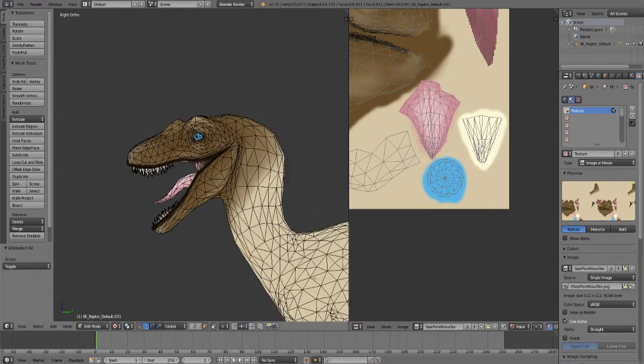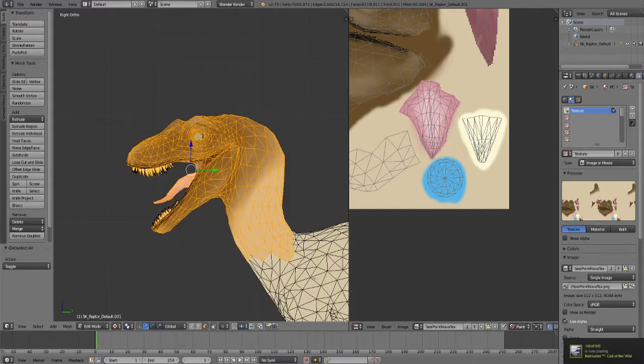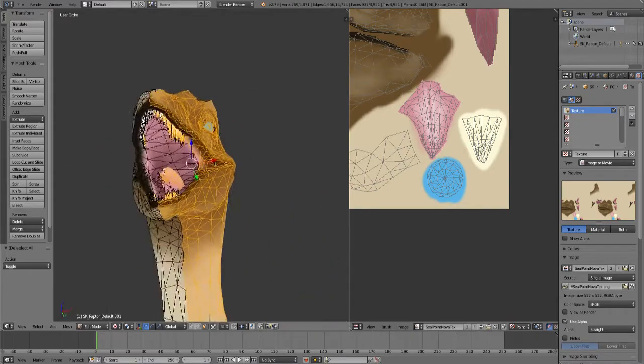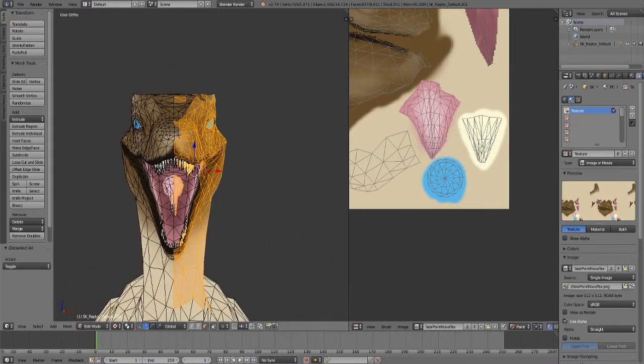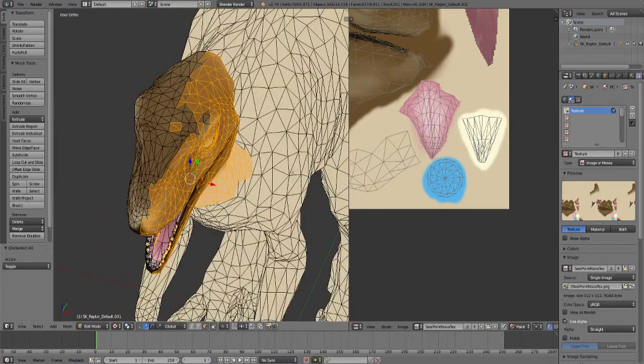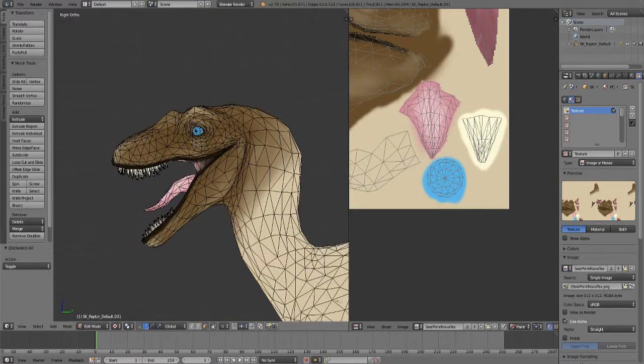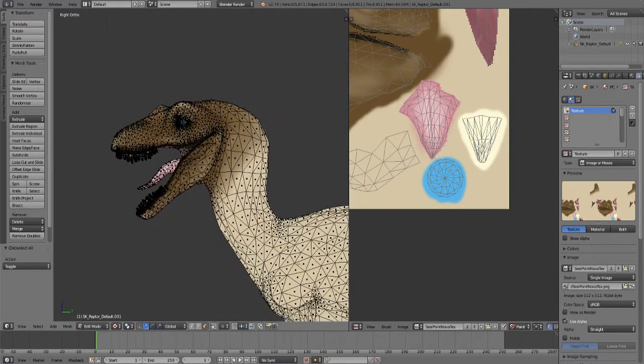Here's a good trick for selecting many faces all at once with the box selection tool. As you can see, selecting this will be very tedious. A better way to select them all is to turn off the option that limits the selection to the faces you can see from a given point of view.